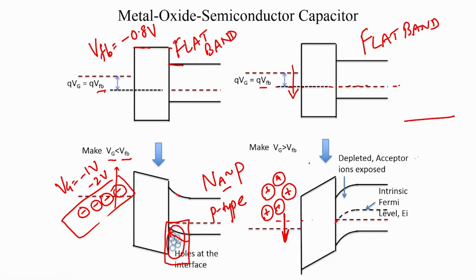So, you have the semiconductor, it initially had an intrinsic Fermi level position, and then after doping we shifted the Fermi level to a more p type semiconductor, and we are using the p type to create your MOS capacitor. But having said that, I have just indicated the intrinsic Fermi level.